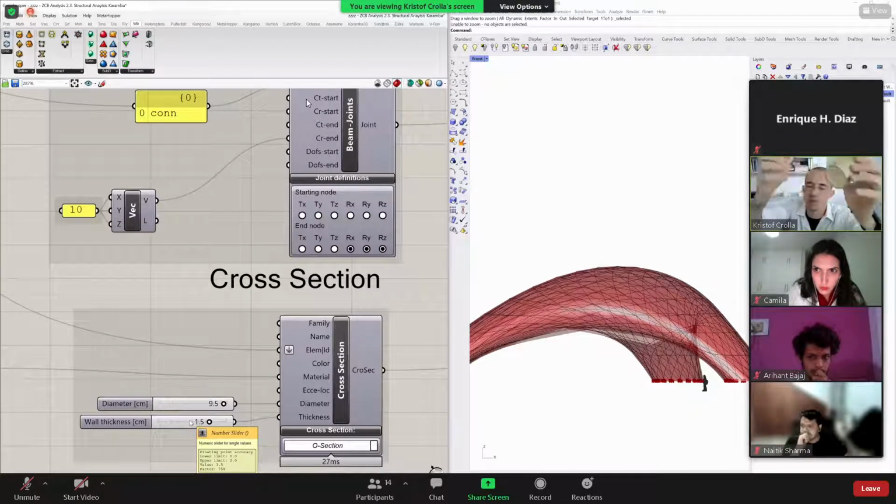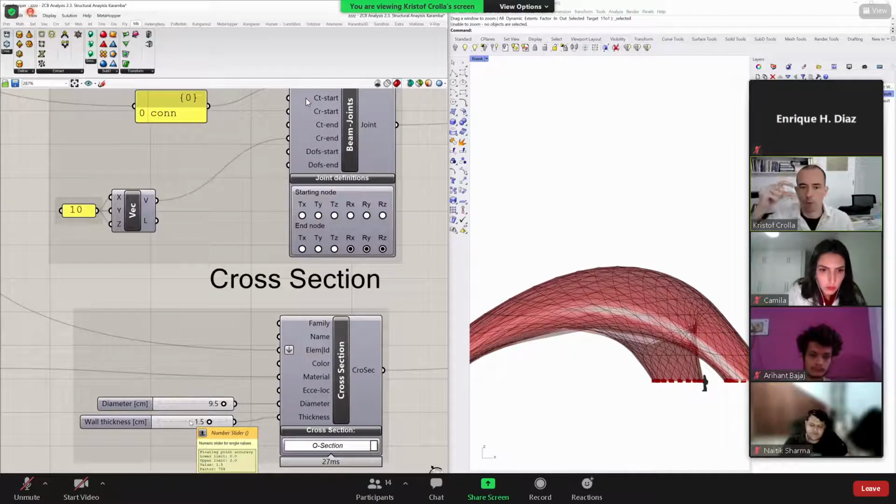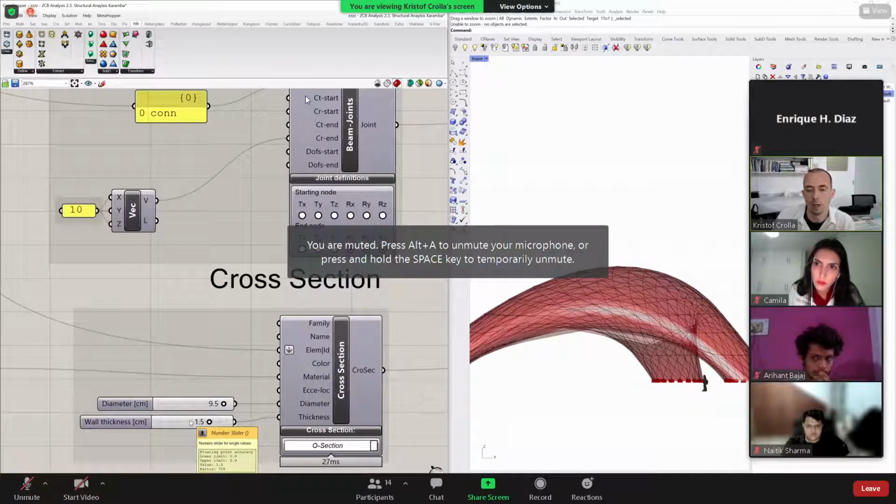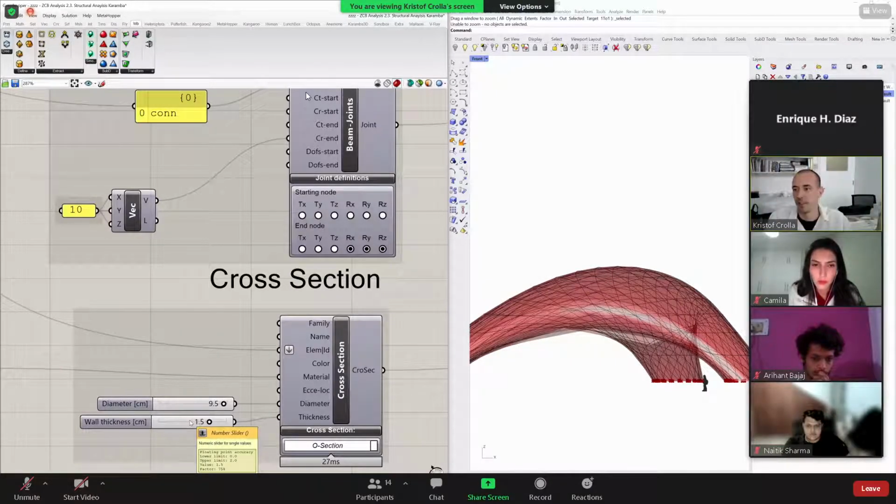Depending on where you are. So this is again just an average that we've taken for the whole setup. But you'll see that the outer diameter matters much more than the wall thickness, because the initial strain that you get responds to the diameter of the pole more than anything else. What I showed you 3 days ago with some of the graphs. A thin stick is much easier to bend than a big stick, basically. So the bigger the diameter, the higher the initial strain is.